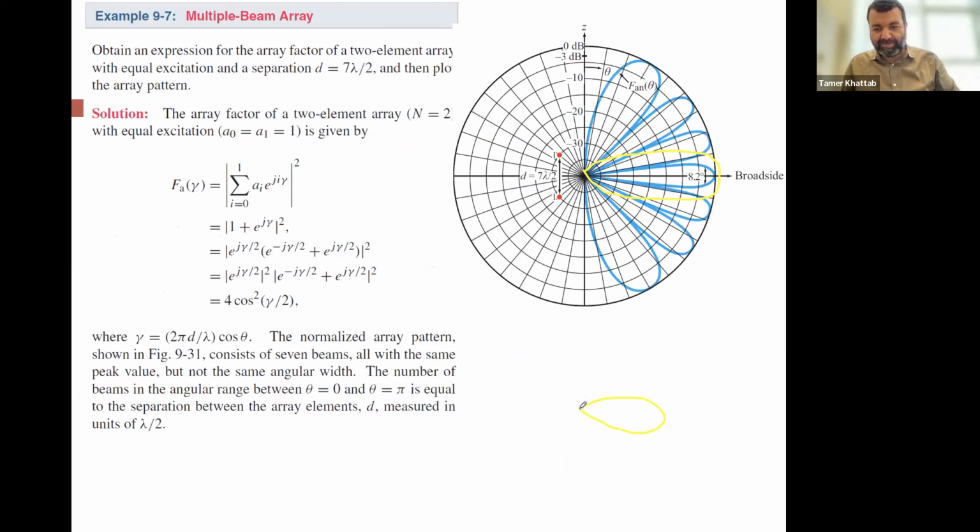We have this main lobe, maybe a side lobe here, another one here, a side lobe on the other side, another small one, and that's it. So that's our radiation pattern, and the maximum coming out of the antenna is in this direction. In all other directions I have less power, and even less, and so on.